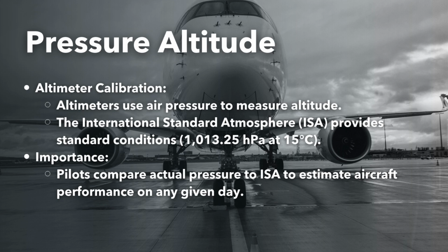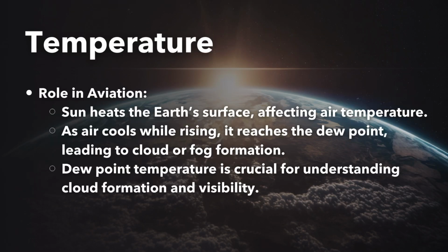Pilots can use pressure altitude to estimate how their aircraft will perform. If the actual air pressure at an airport is lower than the ISA standard, aircraft performance may be reduced due to less lift and engine power. Temperature also plays a crucial role in aviation.